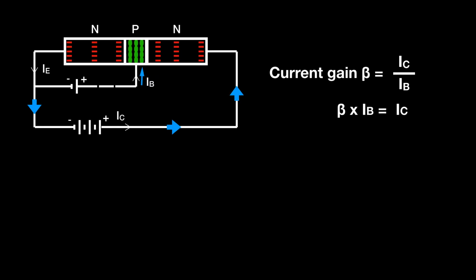By now we should be able to change the subject of the formula where we have three variables. For example, we've been doing it with V, I, and R. We can state V equals IR, I equals V over R, or R equals V over I. Similarly, if beta equals IC over IB, then beta times IB equals IC. You can do that by changing the subject of the formula algebraically, which is probably the preferred method, or you could construct one of those triangles to do it that way.